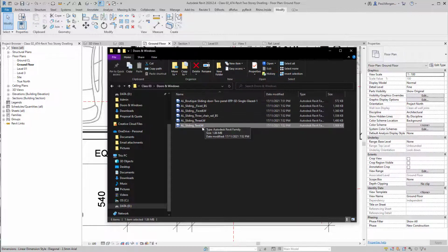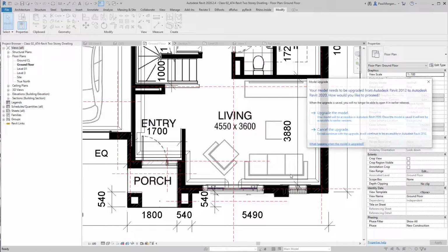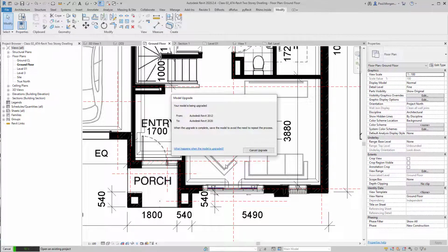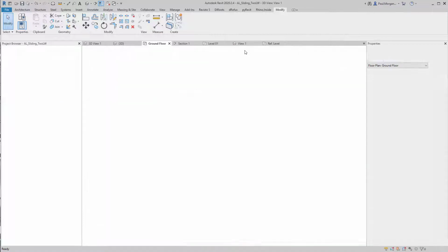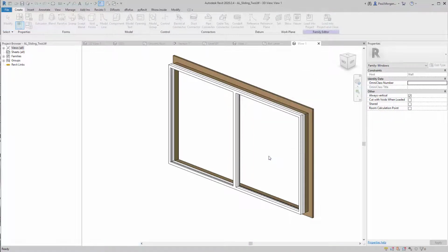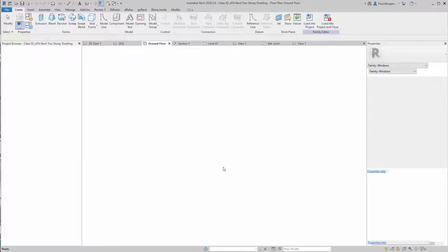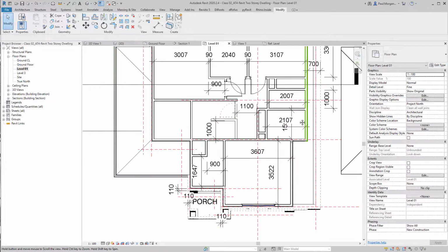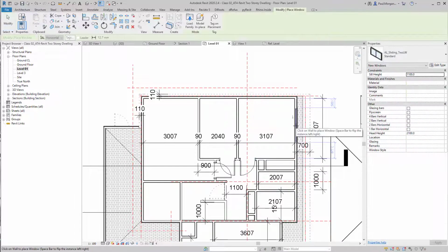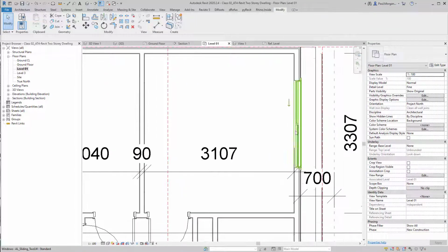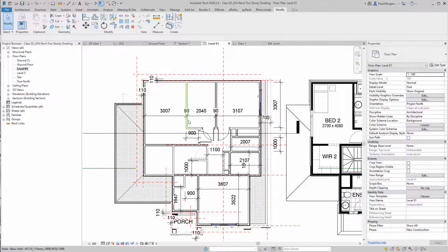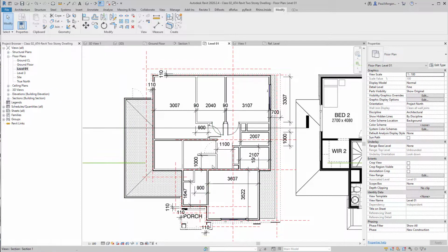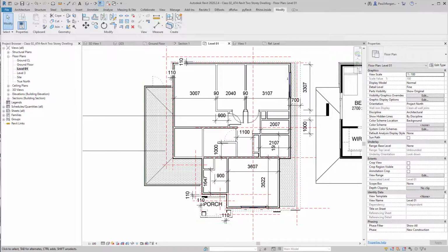That's the brick one. So let's take the 2. So the 2 will be very helpful. So the 2 panel ones are particularly the ones that go in the bedrooms. So I'll upgrade that. Load that straight into the project. So you can see the architraving that goes on the inside. Okay, and then come up to here. And I can't remember exactly where they are on this level, but I'll just start plugging those in. Now, I'm just going to place these into all the walls, and once they're in the walls, we'll then take a look at how to adjust them and dimension those up.